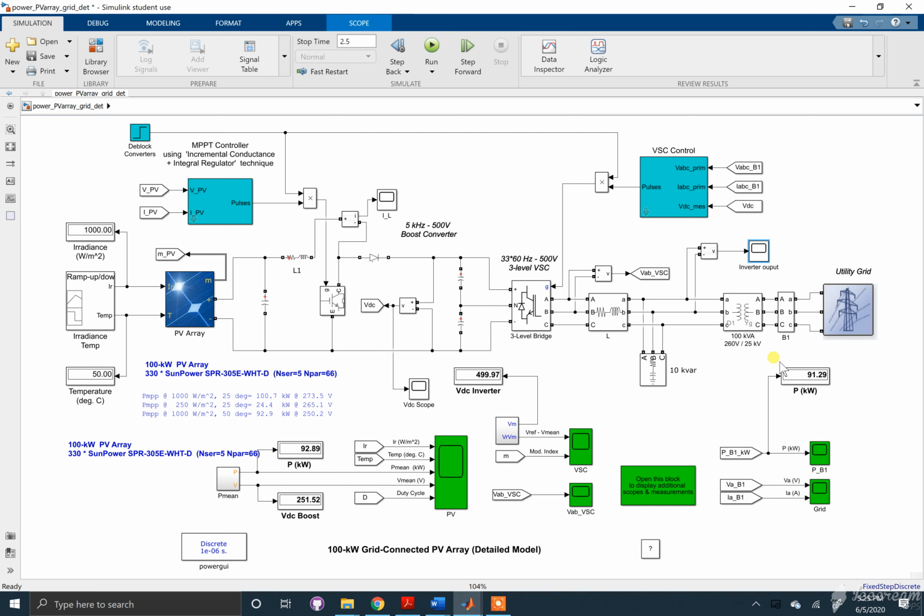Starting where we left off in the previous video, I'll be talking about the MPPT controller. This MPPT controller uses incremental conductance to adjust the pulse to the switch in the boost converter, the IGBT. For this application, where we have a 500 volt output from this array here, you're looking at around 0.5 for the duty cycle, somewhere around there, to get the appropriate voltage boost. And this is calculated with the equation for the duty cycle for a boost converter.